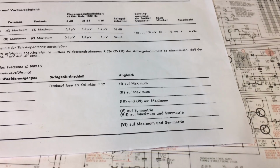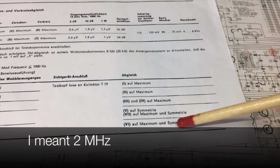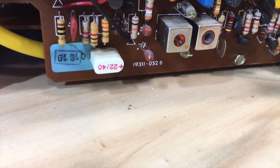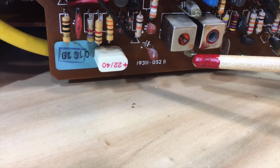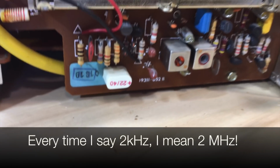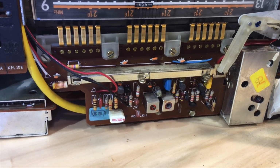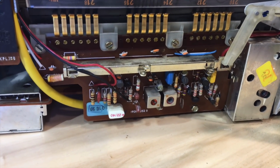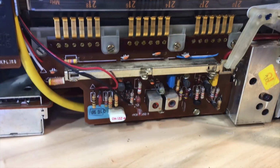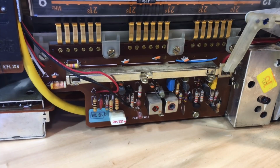You see, 223 is actually before the conversion from 2 kilohertz IF to 460. Let me show you. That there is capacitor 223. And that there is still on the 2 kilohertz IF. It's on that bottom board down there. So I tried feeding a 460 kilohertz signal on there and got absolutely nothing. Then I remembered where I was and I fed 2 kilohertz and suddenly things started to make sense. But there's something else I want to show you first.